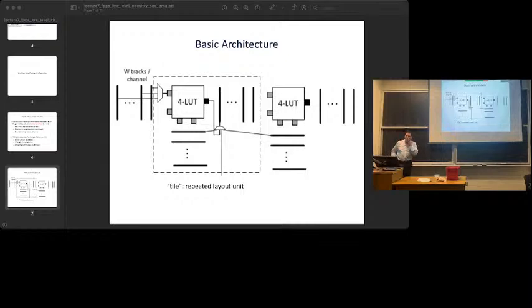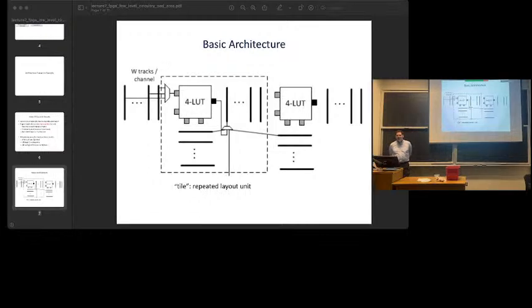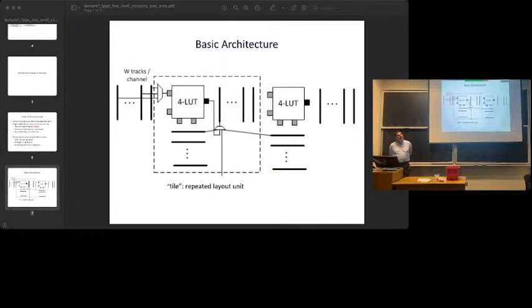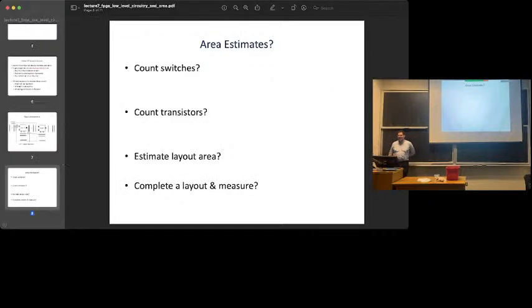I think we can use something more complicated or smarter, like a small CPU, to control it. You could try that, but all this stuff costs area. If you started putting a CPU in to control every mux, then that's going to be big. So dynamic configuration is a good idea, but I think a logic unit is not smart enough to make it easy to change the configuration. Maybe we'll take it offline. I think you're talking about dynamic reconfiguration, which we'll talk a bit about later, but it's probably a bigger topic.